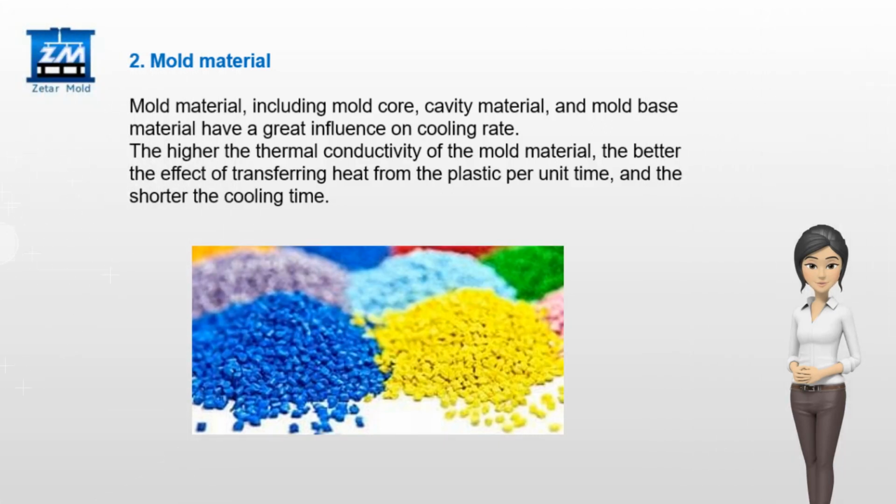Mold material, including mold core, cavity material, and mold base material, have a great influence on cooling rate. The higher the thermal conductivity of the mold material, the better the effect of transferring heat from the plastic per unit time, and the shorter the cooling time.